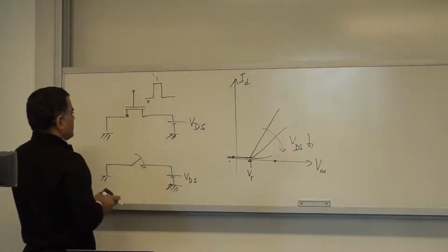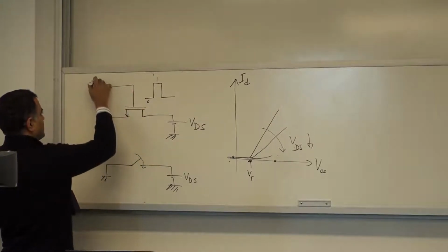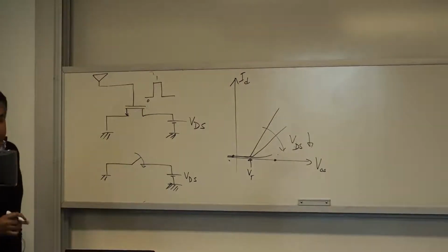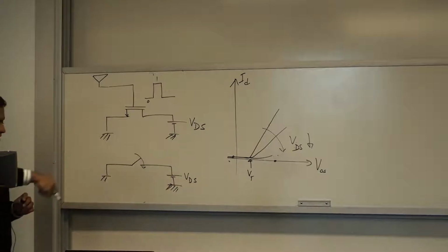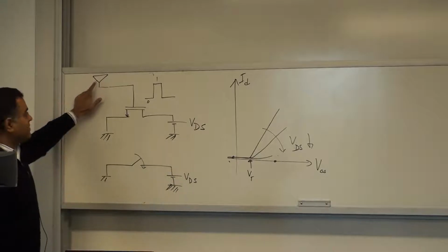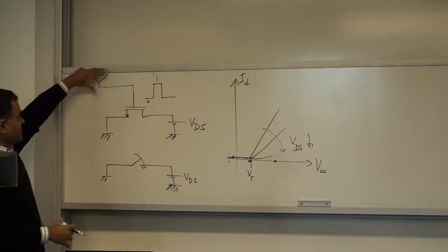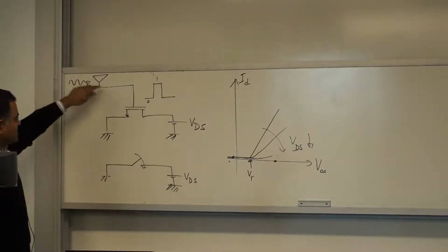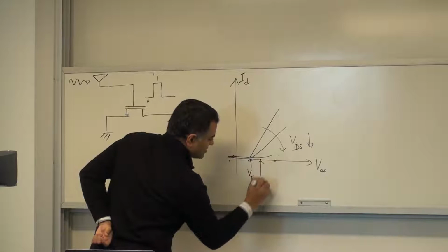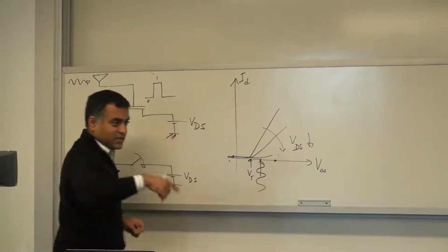The other very important aspect of a transistor is this gate. Instead of being connected to a voltage, it can be connected to what we call an antenna, in engineering terms. What that really means is, if you get your cell phone, the metal wrapped around the edges, that's the antenna, and that directly receives electromagnetic waves from air, and that's a metal. So the electrons in the metal are sloshed back and forth. And what that's doing is it's changing your gate voltage. Maybe you are biased here normally, and then because of this AC signal, the gate voltage starts oscillating a little bit.